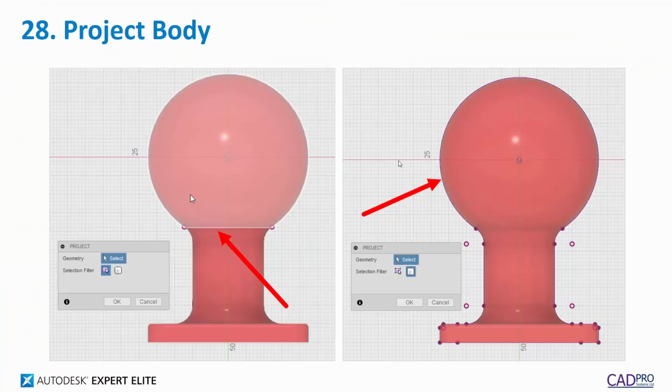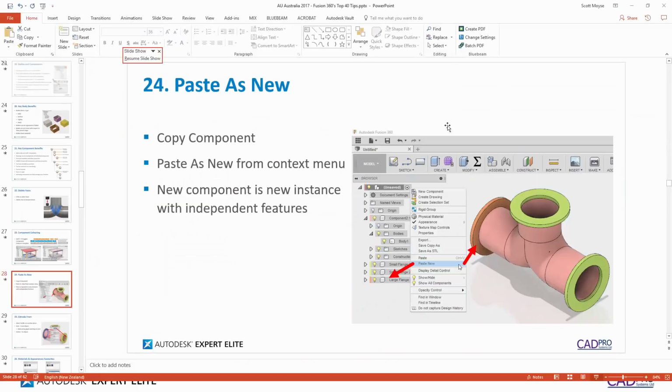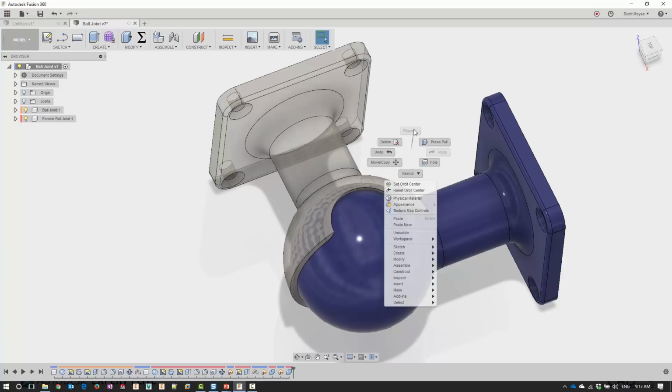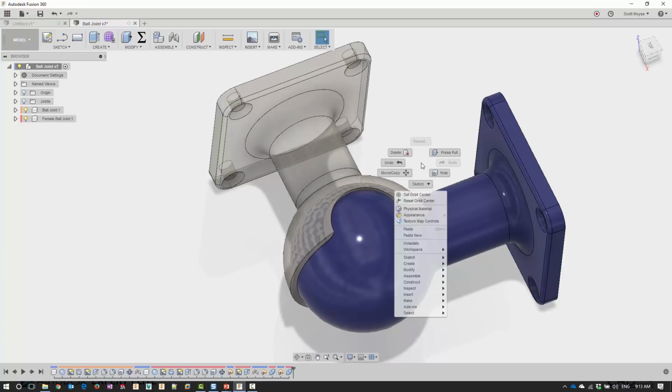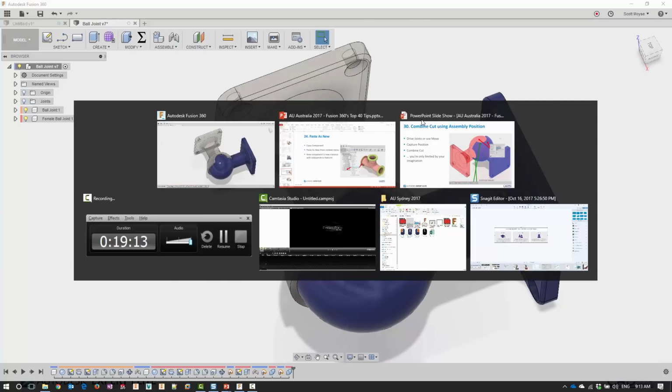We'll go back to the correct repeat last command. I should show you that quickly. Yeah, if you do anything in here, you can right click and repeat, so there's no active command here at the moment for some reason, but you can also, in any of these menus here, use gestures, so you can click and hold in that general direction. So repeat command is right click and sweep up, so it's a pretty quick way, once you get used to it, of repeating your commands.